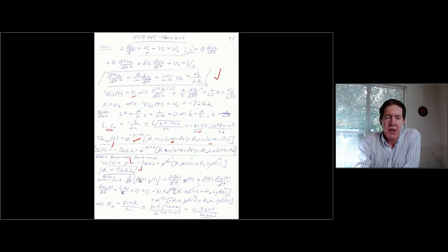What the chain rule says, if you have two functions that are both a function of time, and we want the derivative, is you take the derivative of the first term, f, multiply that by g, and then add to that f times the derivative of the g term with respect to time. So when we do this, we take that derivative of voltage with respect to time, and we set time to 0. Again, that still corresponds to the initial inductor current divided by C, which was equal to 0 because we cleared at a 0 crossing still.